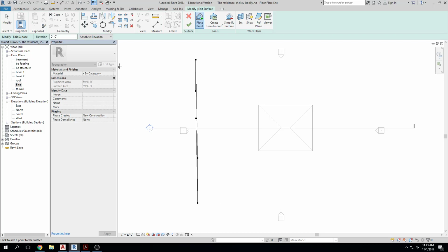There's my 0 marker. Now I need to generate some movement from here this direction, so I'm going to change my elevation to 3 feet and start generating some topos at 3 feet. Oh, okay, that was 3 inches. Well, 3 inches. And then we'll maybe go -2 foot. I'll make this kind of wonky. Here we go.